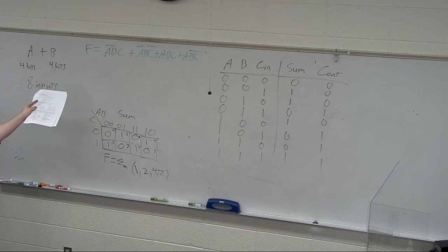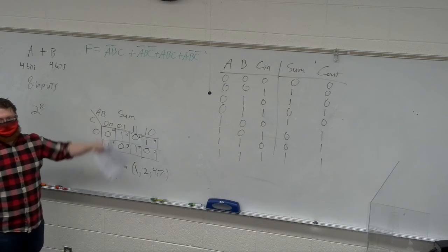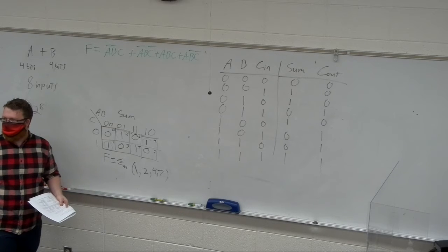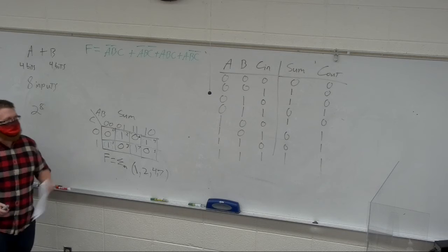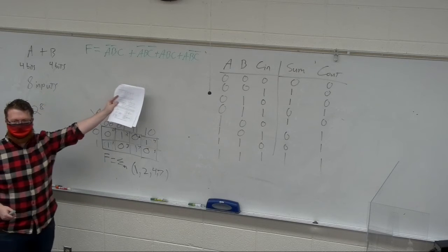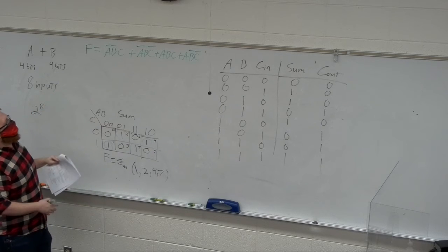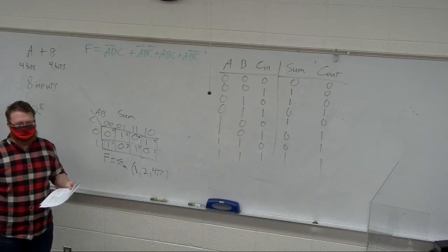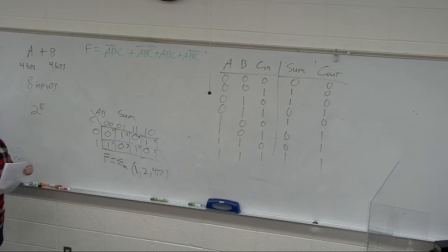So that's our equation. We can't really simplify that. This is an optimal. Now, what is it optimizing again for? Speed. Propagation delay, yeah. This is a minimal propagation delay circuit. It is also fairly easy to turn into universal gates, which we will get to. That's actually a really fun chapter, is design from these equations.